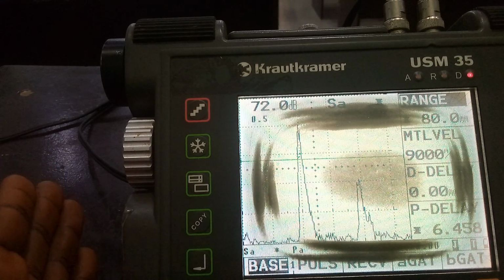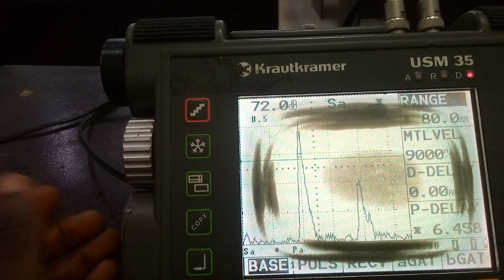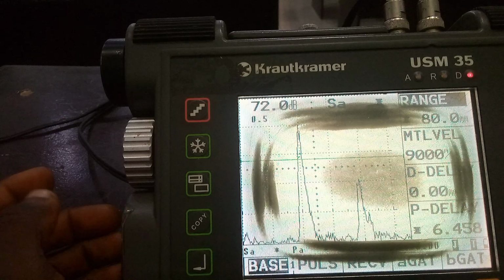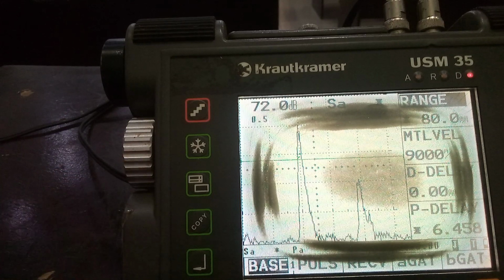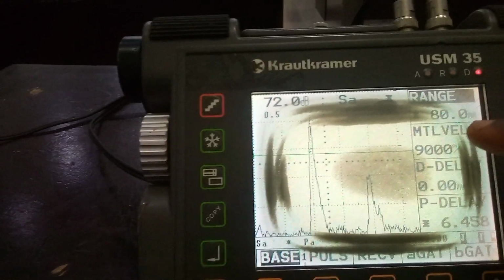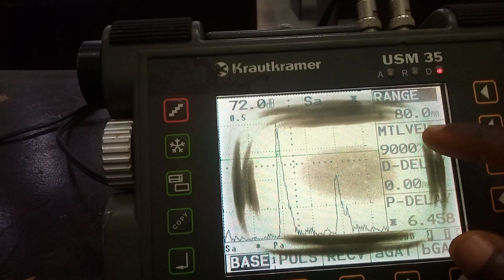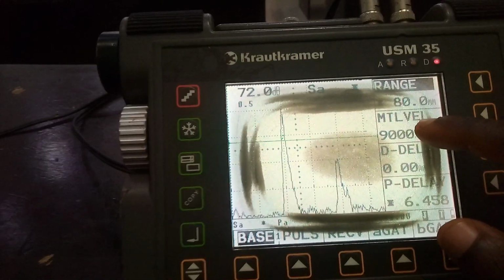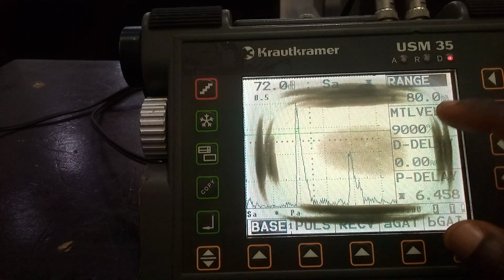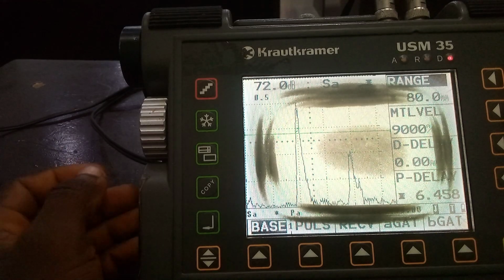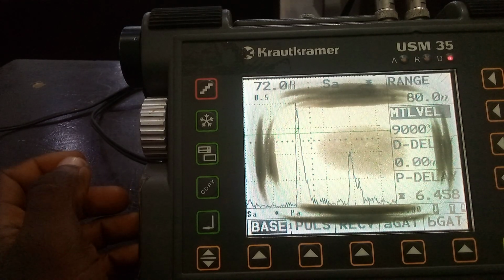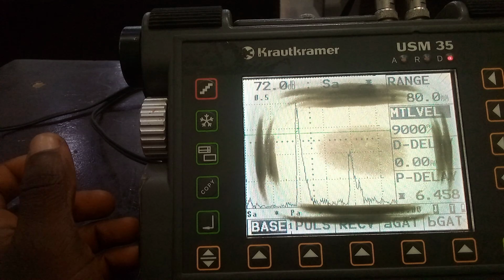So whatever you are using, just multiply it by 4. That gives you the range for that particular material. So the next thing we will do, this velocity, longitudinal velocity of sound. We're going to set the longitudinal velocity of sound in carbon steel. So here, or in steel, we'll set it here. We'll click on it. It is supposed to be 5920.